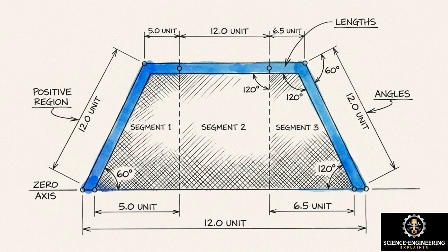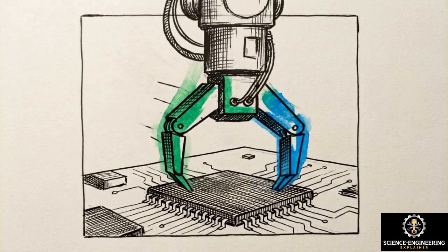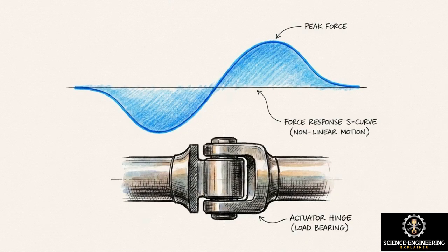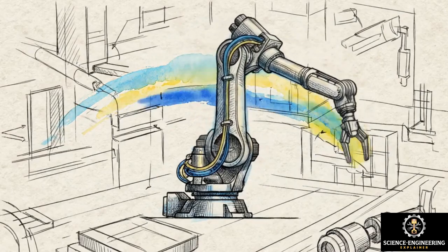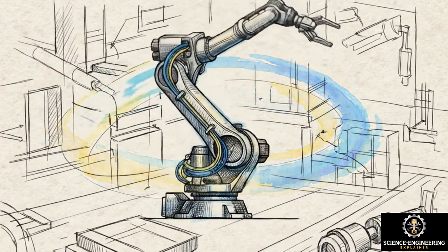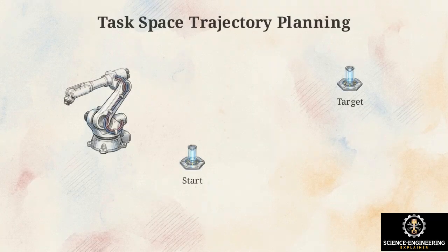Because acceleration is held to piecewise constant values, the system never generates a negative velocity command. Engineers specify trapezoidal profiles in industrial robotics to guarantee the arm will never mathematically overshoot its target position. Generating a trajectory for a single, one-dimensional actuator is a solved mathematical problem. But scaling that logic to coordinate a highly complex 7 degrees of freedom manipulator requires a choice in how the system processes spatial geometry. The first architectural approach is task space trajectory planning.